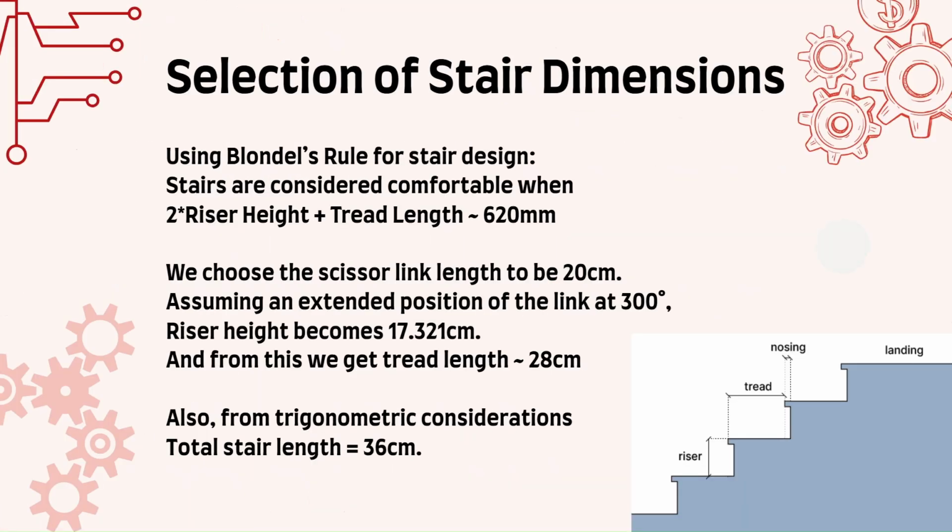Hello everyone, myself Dhruv. Starting with the selection of stair dimension, to ensure comfort, we applied Blondel's rule, which states that 2 times the riser height plus tread length should be close to 620 mm. Using the simple ergonomic principle, we selected link length to be 20 cm.